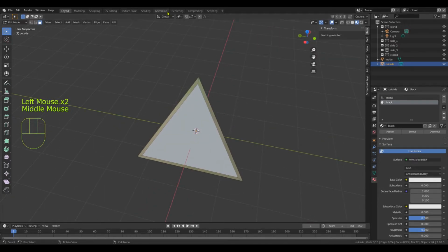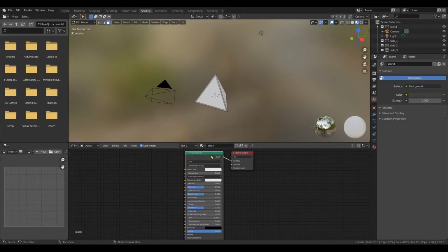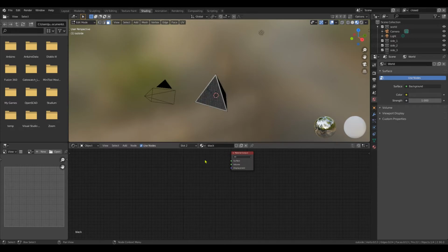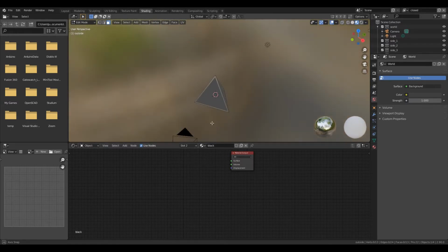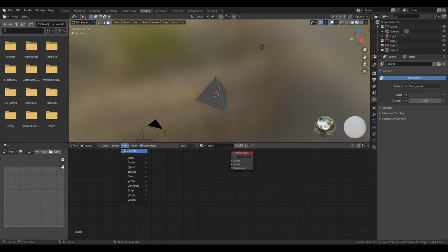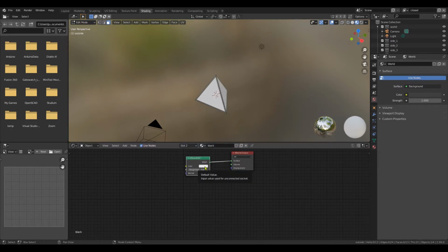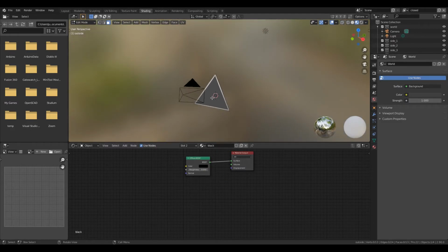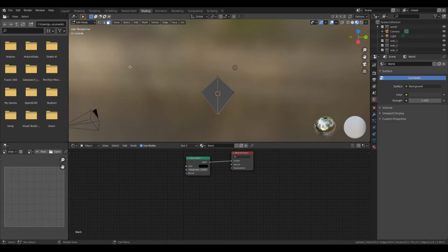And we want this to be perfectly black, so we go to shading. We remove the Principled BSDF node, and I think black is already the default value for surface, so this should already be enough, but I take the Diffuse BSDF node. And we have to set the Diffuse BSDF to black, of course. Since we want the 3 closed faces to be perfectly black, a holdout material won't work as material here. At least not for the compositing trick I presented in this tutorial.